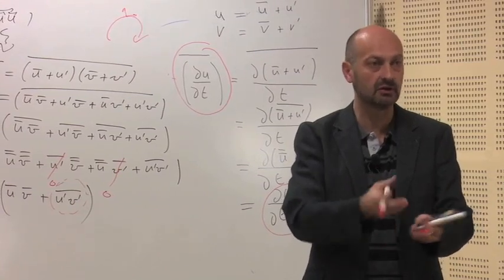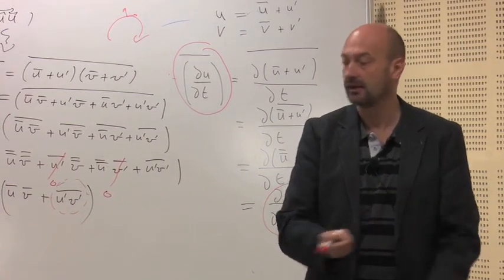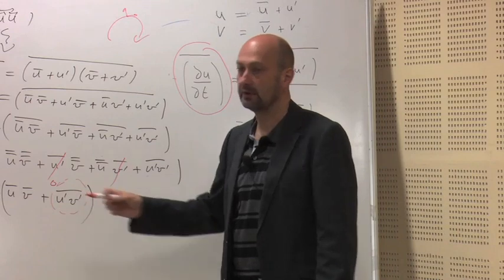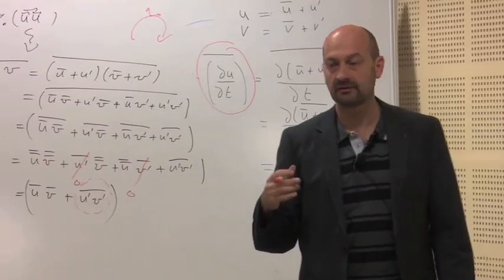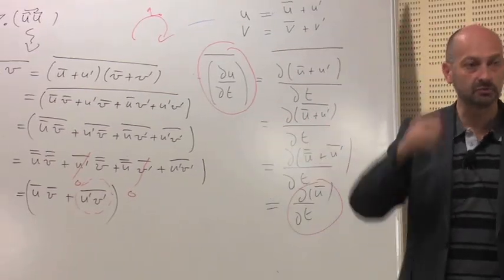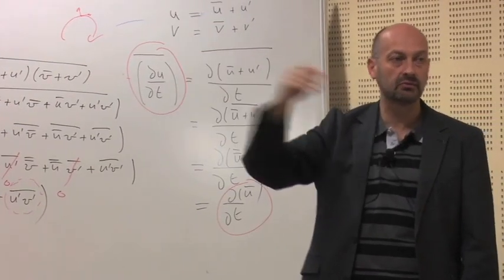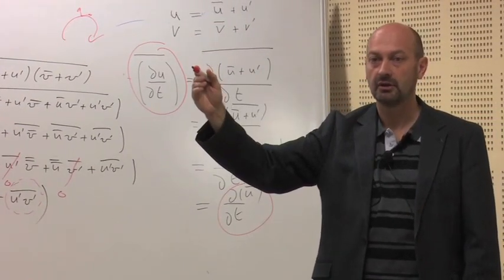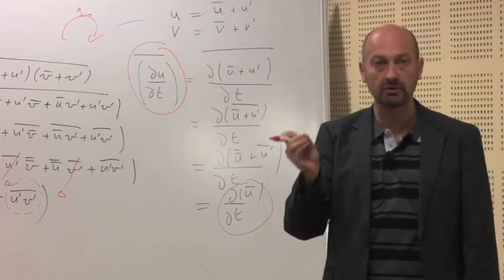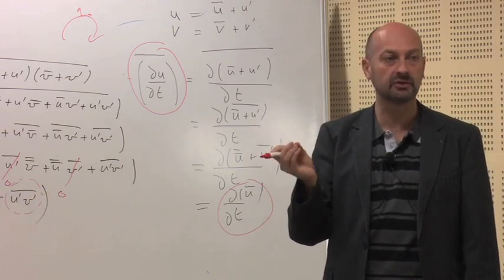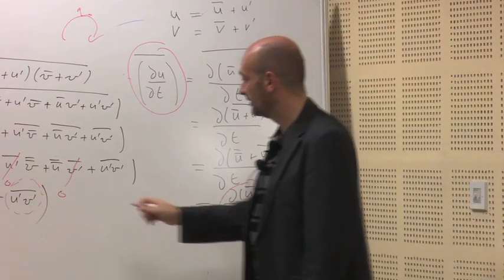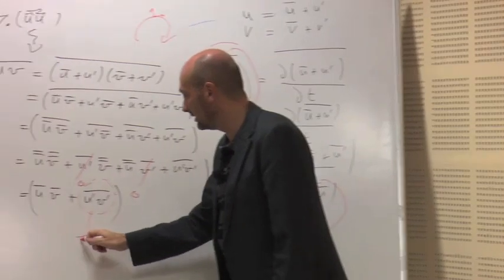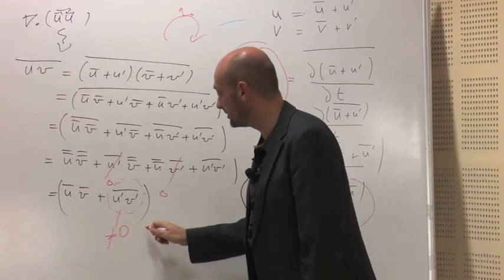It is complex, but still you have the vortices. So u prime and v prime, you may assume that these are stochastic variables because you see fluctuations like a random variable, but these two variables are correlated. There is some correlation. So this is for sure non-zero in turbulence.